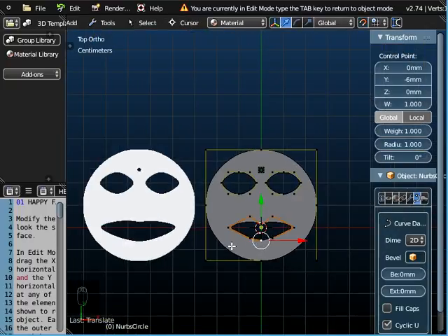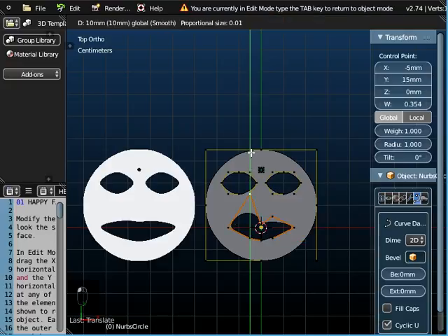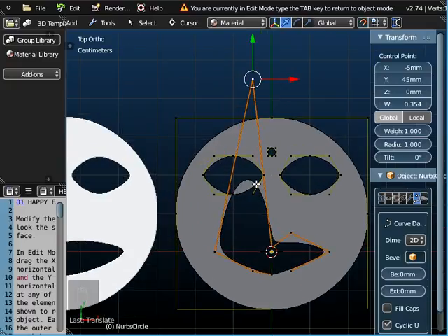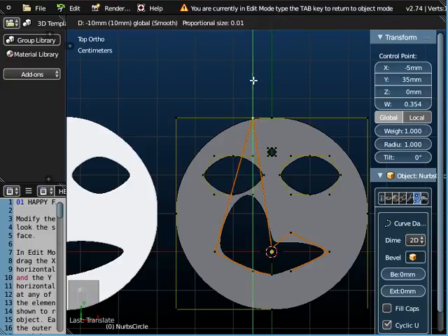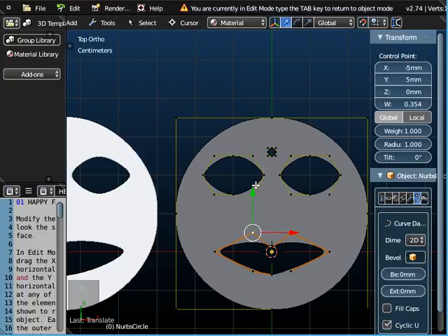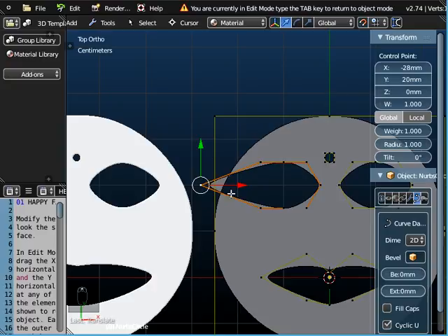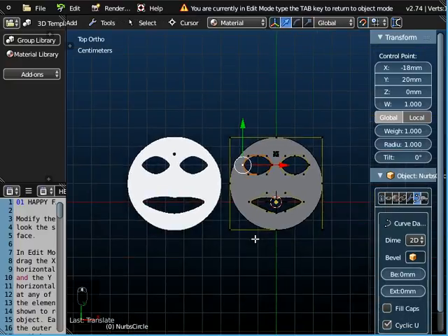Okay, now the actual layout and style of this is entirely down to you. But one point to note about these objects is it's not a good idea to have them crossing over like that. This won't print. This will make a right mess of things. So as you're moving these objects around, you do need to make sure that they don't overlap each other. Otherwise you're going to have all sorts of problems. Similarly, you can't take this outside here. That's a strange area. It's not going to print. Okay, so you do need to be a little bit careful about that.